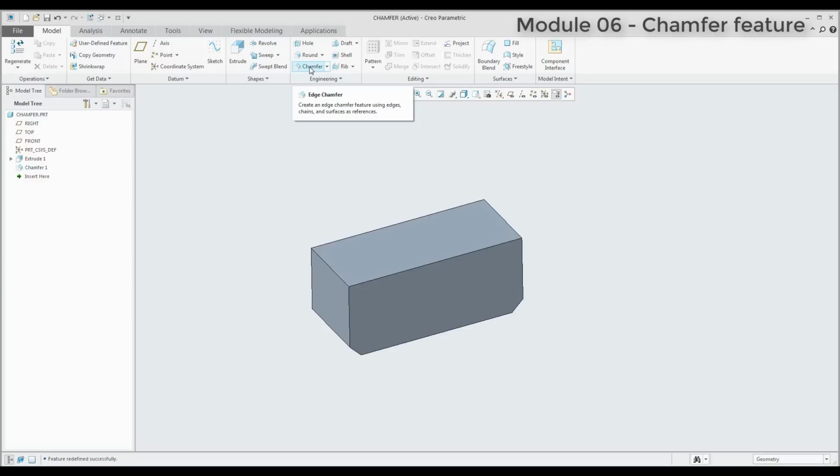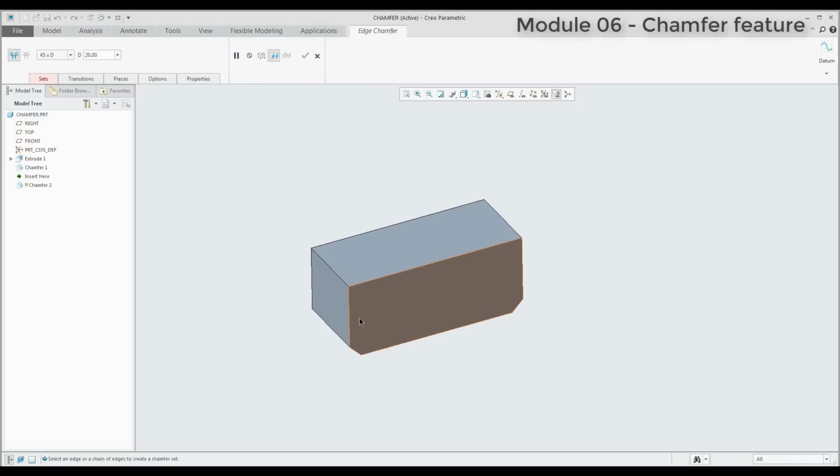So I'd like to create the chamfer on that edge, but I don't want to use only this one edge, so I select the right mouse button, and then the system shows me information that it will create the chamfer on the intent edges from the extrude feature. So you can use the vertical intent edges. Yeah, so we only select that. Right now the system really quickly creates the chamfer here.